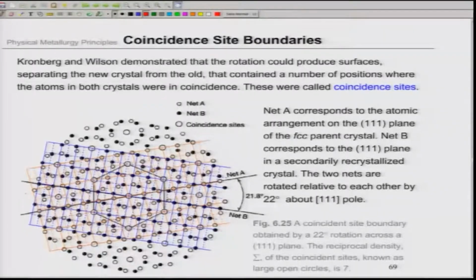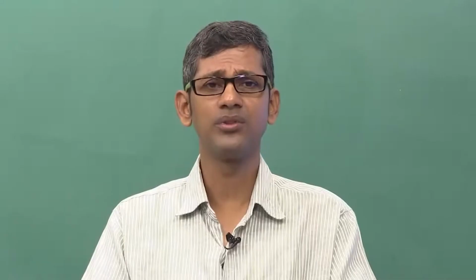That means, what we are basically doing here is that if I have two different crystals side by side, we can have the bonds formed between the atoms of the two crystals by rotating one of the lattices with respect to the major axis of the crystals by a certain amount, by certain degrees of rotation. In fact, this rotation is basically done to make these points or the atoms sitting on each other coincide, so that they can form bonds, but not all the atoms actually.